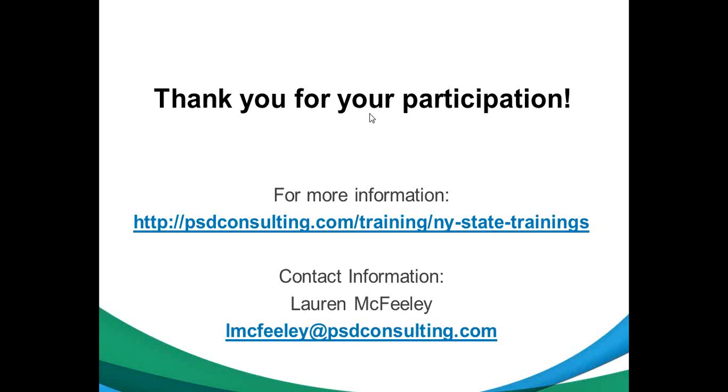Johnson Controls, you really need to know their systems, like be a controls vendor and know them, or have one of them help you get the data out. Certain systems are just easier to set up the trend historian and get the trend data out. Some are very difficult to understand and kind of locked down. So to me, that's usually the biggest cost on our part, getting the trend data from the building automation system.